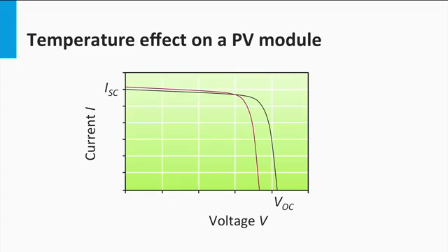On the other hand, if the temperature were to decrease with respect to the original conditions, while the irradiance were constant, the PV output would show an increase. The minute increase in current with temperature can be explained with the fact that carrier concentration and mobility increase in the semiconductor with temperature. This is consistent with our basic understanding that a semiconductor, unlike a regular conductor, exhibits better conductivity with increasing temperature and is a perfect insulator at absolute temperature of 0 Kelvin.